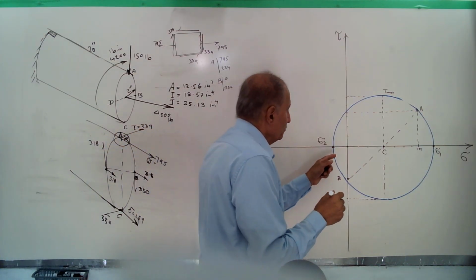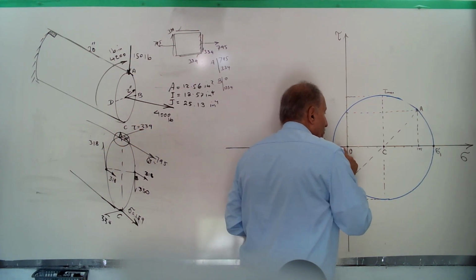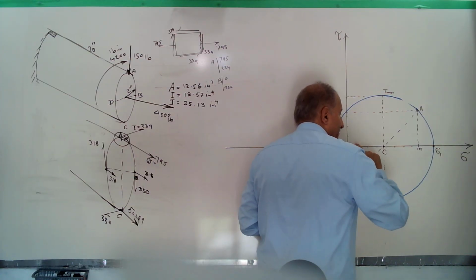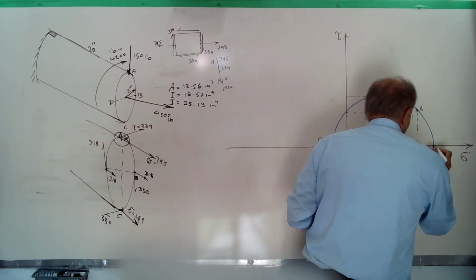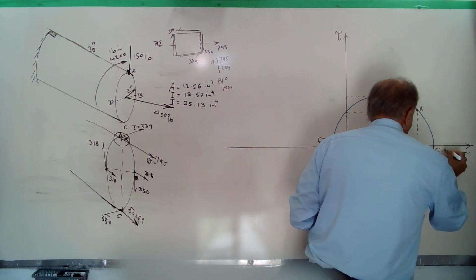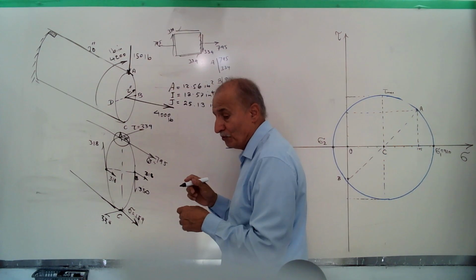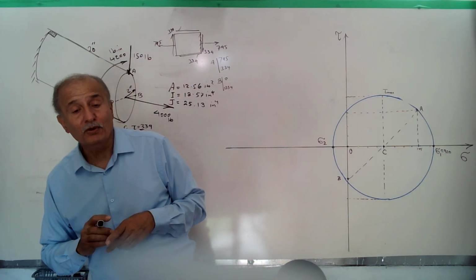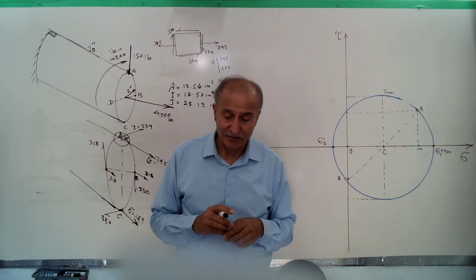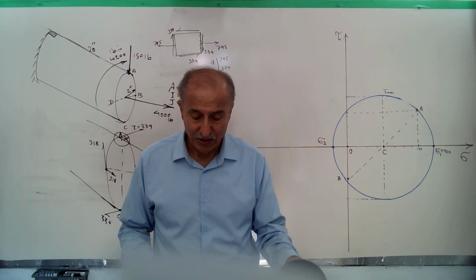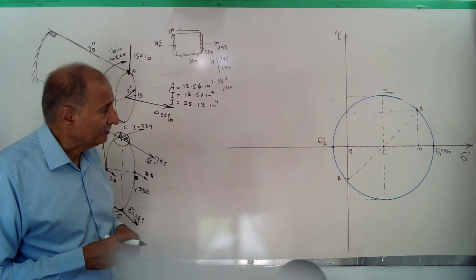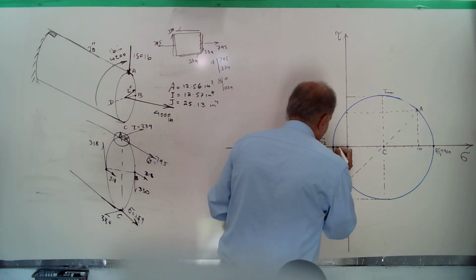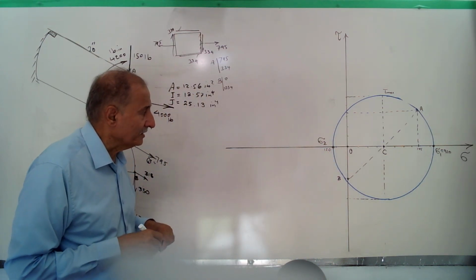Then you must measure from point O, the origin of the coordinate, to sigma 1. You will find out maybe sigma 1 is 920, approximately. If you want the exact value, you must use the formula for Mohr circle. Maybe you reach that. And what about sigma 2? Sigma 2 is negative, and if this is 100, it should be 120, something like that, minus.